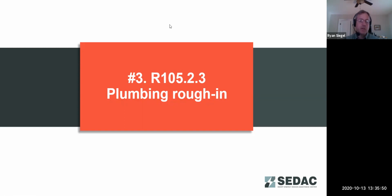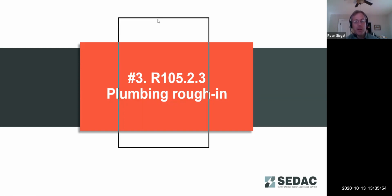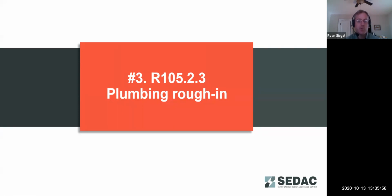And third, where should the air seal be located around fenestration? All the way around the frame at the interior edge, top and sides around the frame at the exterior edge, all the way around the frame at the exterior edge, top and sides around the frame at the interior edge, and there isn't an air seal required. Again, we're talking about the air seal on this one.